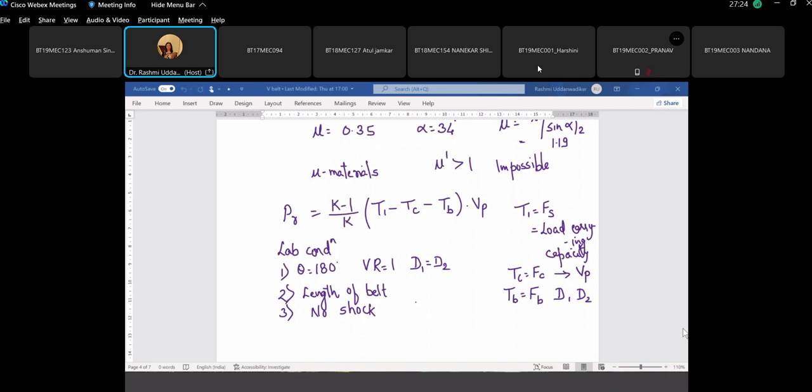And the last page will be giving you the correction factor depending upon light duty, medium duty, heavy duty and extra heavy duty. And we'll be using this correction factor as well. There's one more page which is giving you the number of belt, formula for number of belt and the dimensions for the standard V grooved pulleys. So I'll tell you how to read this design data book, and before we actually start solving the problem, let us quickly see what are these correction factors and how to find out the number of belts. Should we start?